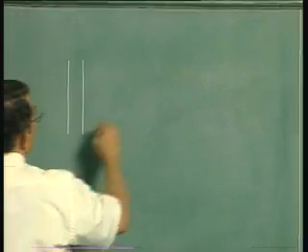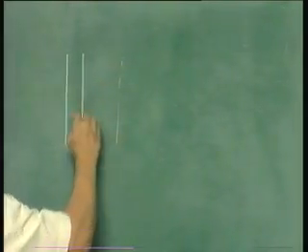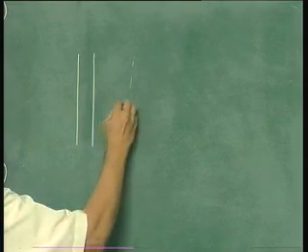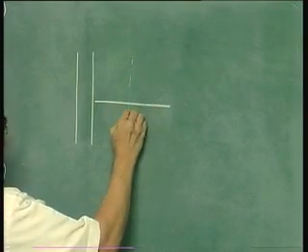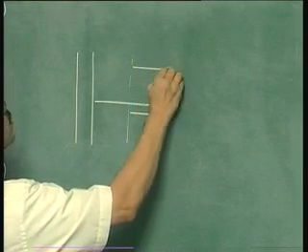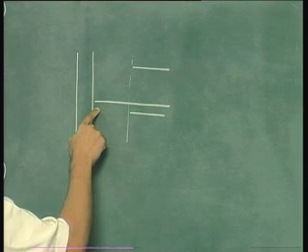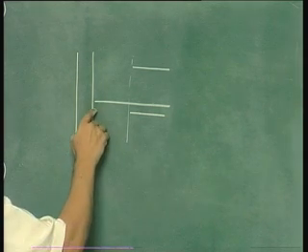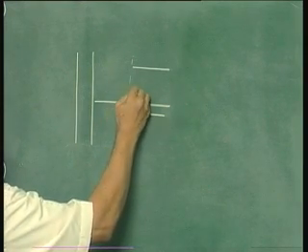Supposing I assume a p-type substrate, then at inversion the energy band diagram is as follows. You first draw the Fermi level. In the bulk, these are your bands. Now at the interface, what you know is that the surface concentration of electrons is equal to the bulk concentration of holes. So let us draw the intrinsic level here in between.